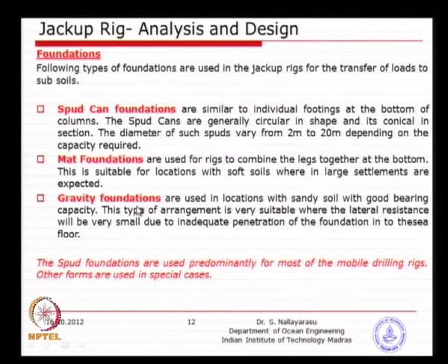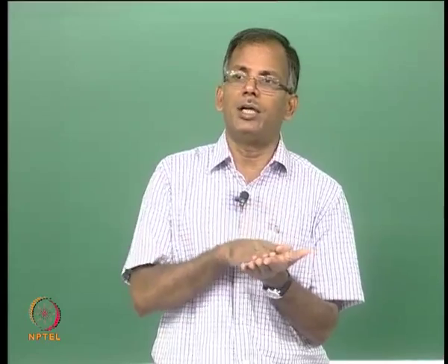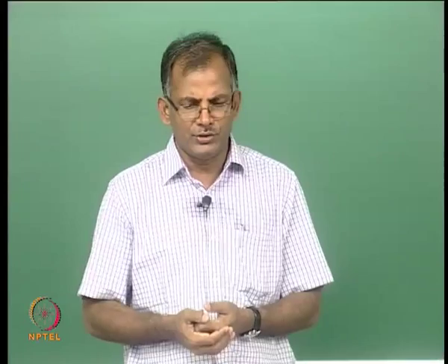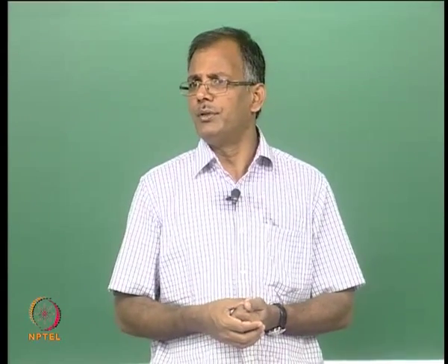Gravity foundations are very common whenever the soil is very good. Basically the structure is made so heavy that the stability against horizontal and overturning loads is achieved by its own weight, and the vertical stability is very simple because the soil is good, you have enough bearing capacity. So, that is the type of foundation. It is even used for offshore platforms, gravity type concrete structures.